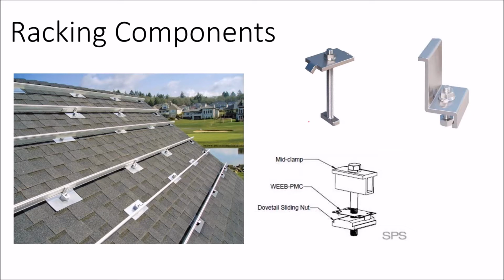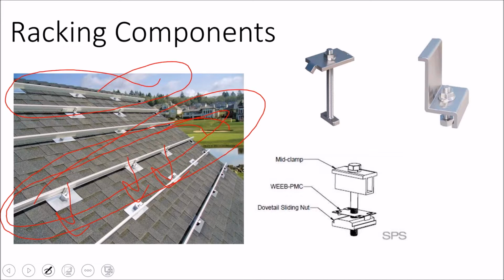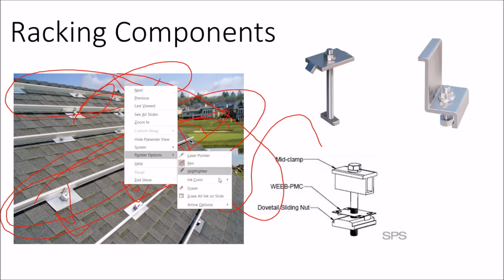So anyway, it's worthwhile to do your racking engineering. And on the fire safety concern, basically by using this additional rail and going into each rafter, you're providing some additional support strength along that roof surface. And so, firemen right now, they're scared of solar because this does not have the 3 foot up off the top and 3 foot off the sides for a fireman to get up on the rooftop and cut a hole. And that's not uniformly enforced across all jurisdictions.